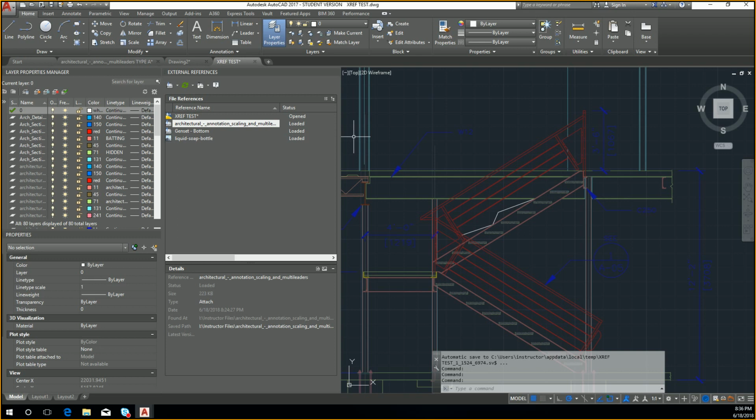So from here, practice unloading it as well, because you can unload your model now. So let's say draw something on here in this space. Draw some lines referencing the height of the door. It doesn't have to mean anything. And then right click and practice unloading it. So it takes everything away, but you can still reload it. The way to break it is you detach it. If you're completely done with it, you detach, and it's gone.